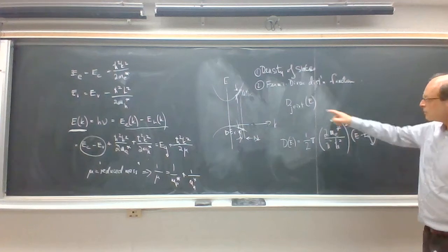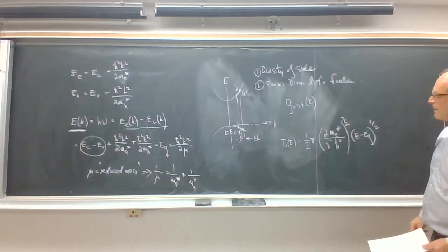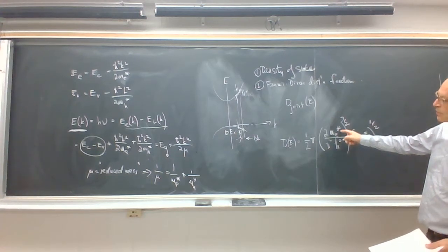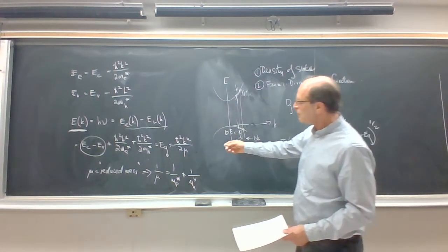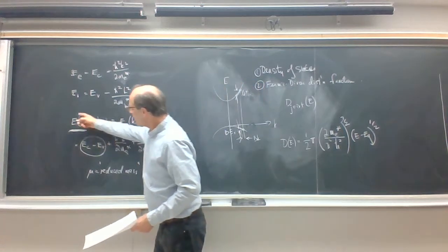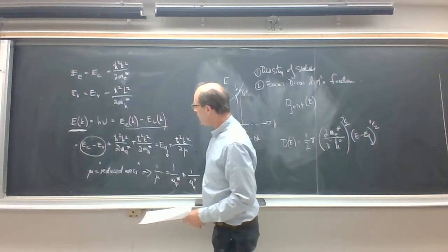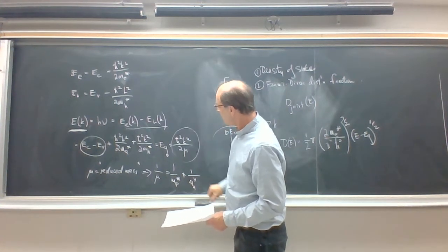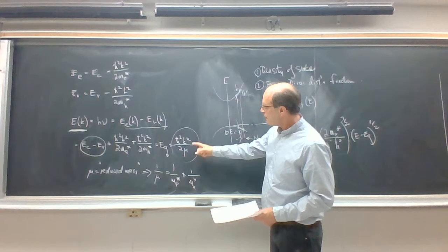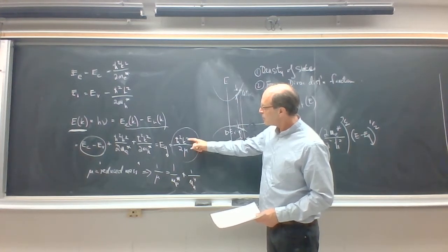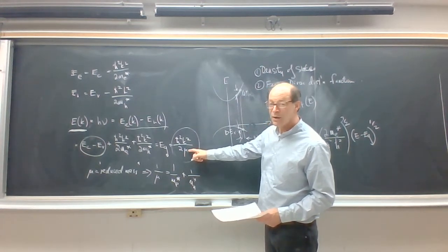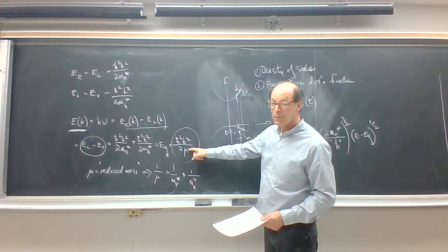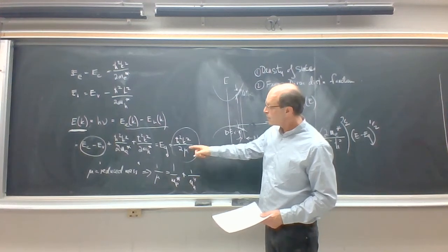The change we're going to make when we look at the joint density of states is, instead of just considering me star, we're going to consider the density of states relevant to this new quantity we're calling E of k, and it looks very similar to the original density of states, except in place of me star or mh star, it contains this quantity mu, the reduced mass.